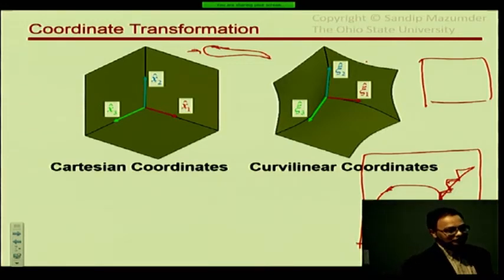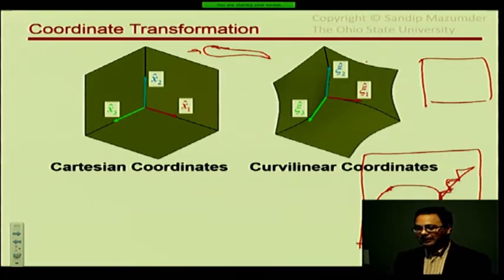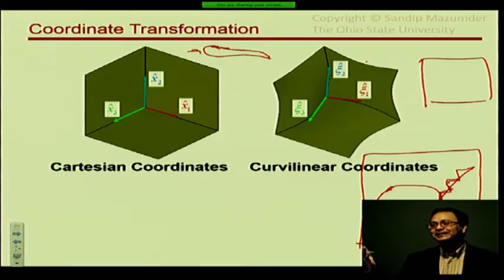If you want to do, let's say, heat conduction in a plate which has a hole cut into it, a staggered or stair step approximation like that wouldn't give you really unacceptable solutions. Fairly decent solutions you would get. But think about doing that for an airfoil. What would it do to your drag? There's no meaning in doing that kind of calculation with a stair step mesh. It's pointless.